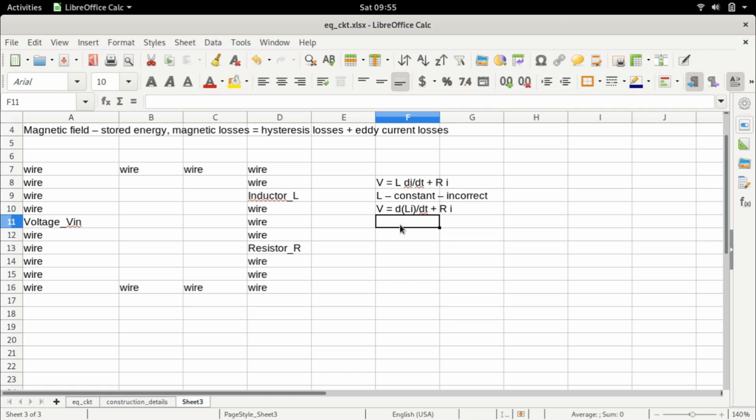So this equation, as we all know, L into I is equal to psi, which is the flux linkages of the induction motor. You can say of the stator, but for now we just say of the motor, because we are representing the entire induction motor as just one inductance, right? This entire description is for the sake of starting to write some equations so that we can figure out what's happening. So we have now come to this equation.